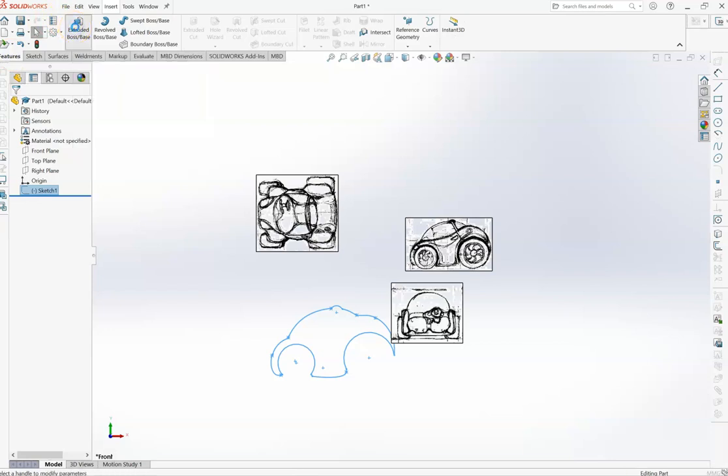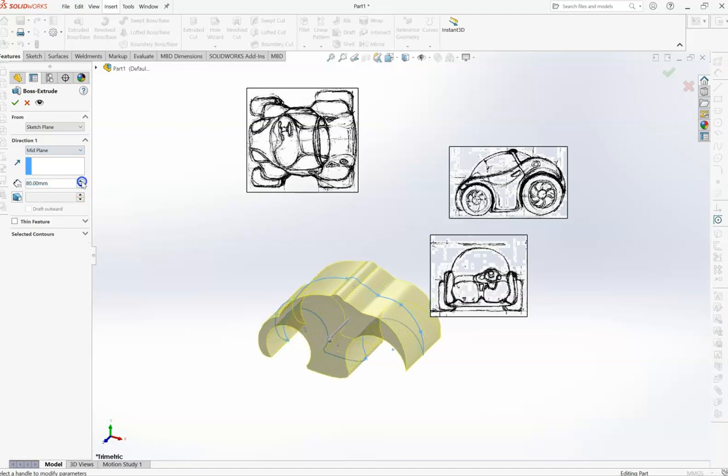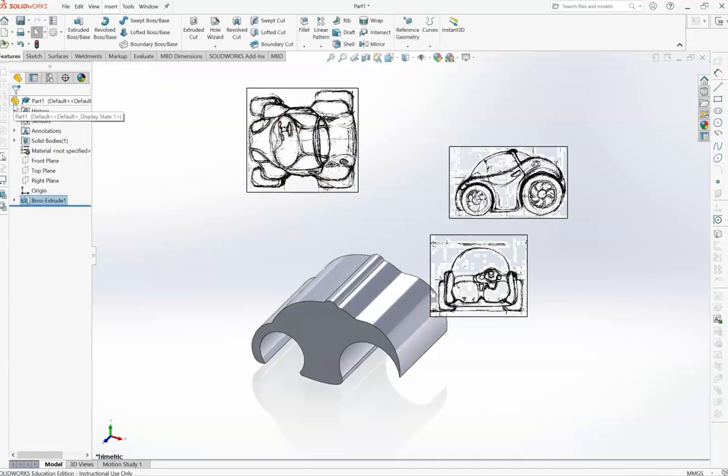that shape. Now, because I've got the origin in the center, I'm going to extrude mid-plane, and I already have my measurements. If I've done this on paper properly, I should already have my width measurements. I'm going to go with 90 millimeters. No, I'm going to go bigger than that because I might want to cut it down, because this is how boxy my top view is, so it's quite fat. So let's go with big, and we'll chop it down.